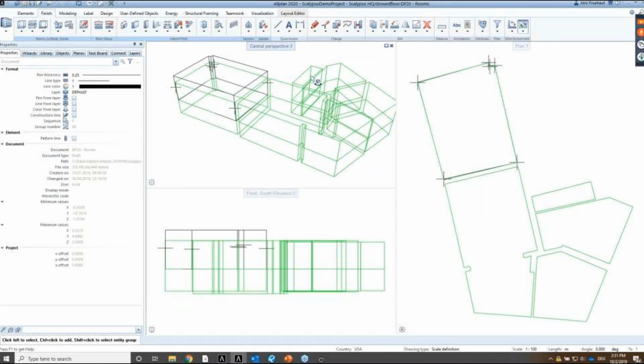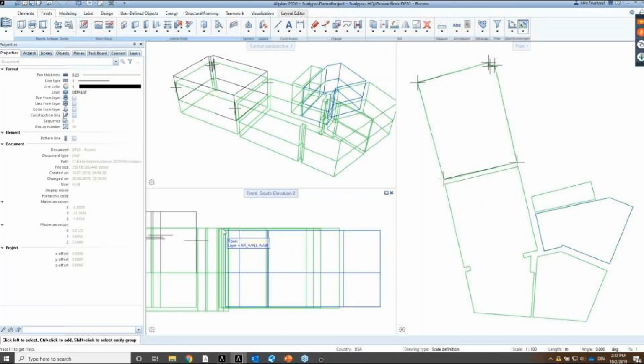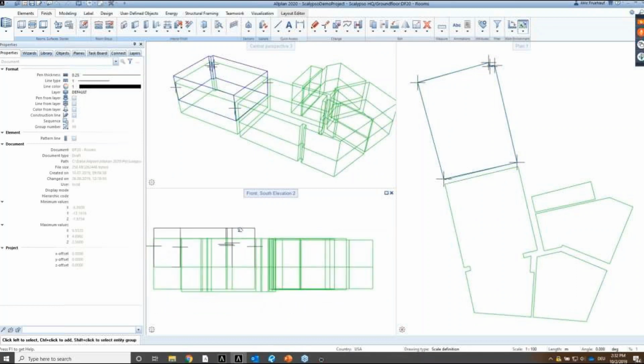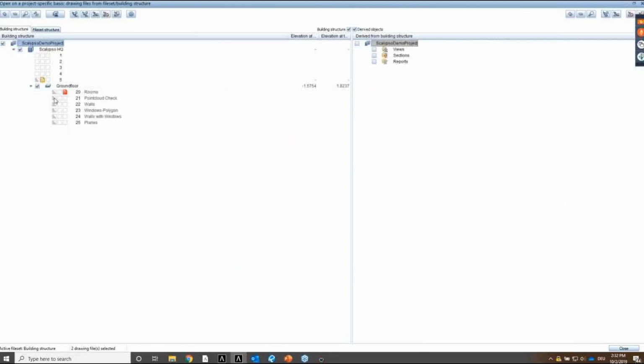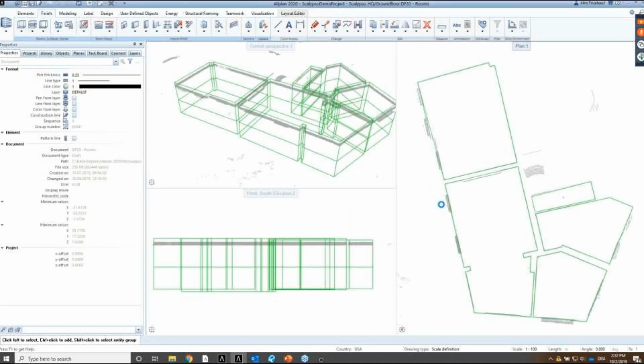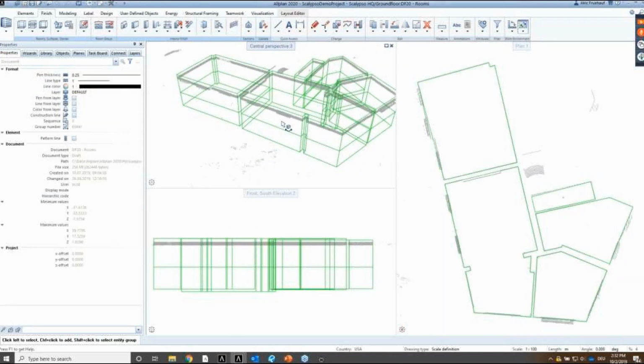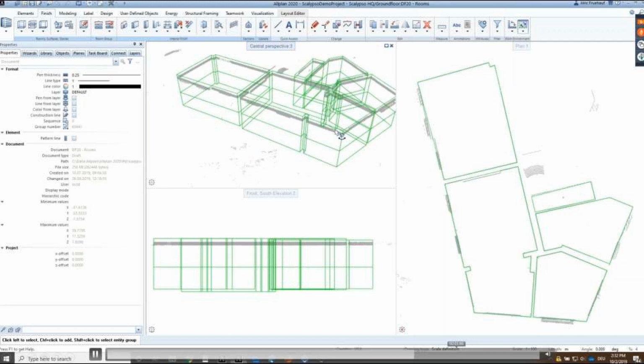What you can do with the premium version of Calypso, so this is from their provider, is to import volumes or surfaces directly. So instead of using some control points and drawing the 3D model yourself, you can also import that, which for complex structures can be really helpful. So to get the initial BIM model of an existing building, that can be a very nice workflow.